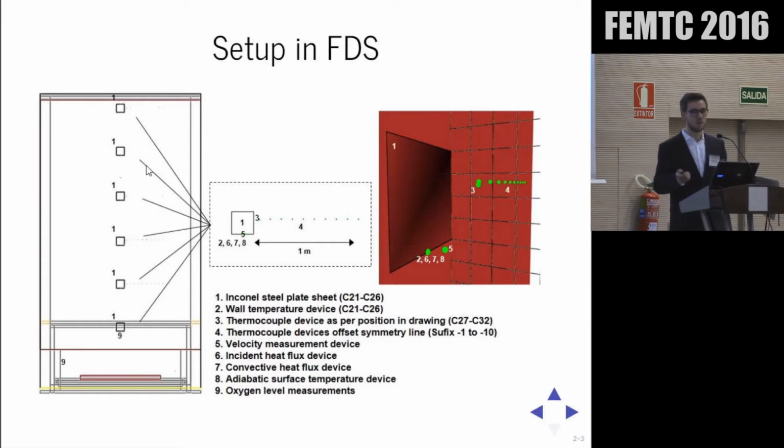A plate thermometer is basically built up by a steel plate with a thermocouple welded on its backside, and behind that you have insulation fiber boards. This was emulated in FDS by applying surfaces with steel and insulation materials and their thermal properties. Behind that, we fitted a wall temperature meter that measured the temperature of that exposed surface in FDS. That was how it was emulated in FDS.